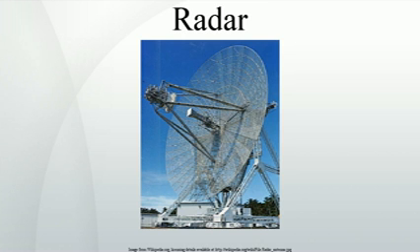Principles. A radar system has a transmitter that emits radio waves called radar signals in predetermined directions. When these come into contact with an object, they are usually reflected or scattered in many directions. Radar signals are reflected especially well by materials of considerable electrical conductivity, especially by most metals, by seawater and by wetlands. Some of these make the use of radar altimeters possible. The radar signals that are reflected back towards the transmitter are the desirable ones that make radar work.